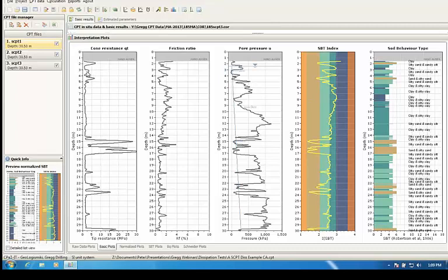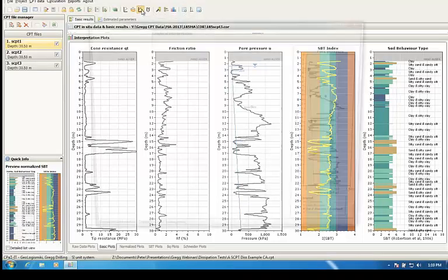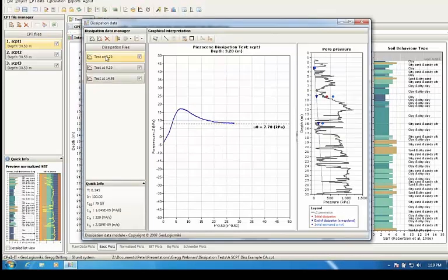Pore pressures went negative, but there are probably some positive pore pressures, certainly above where the dissipation test was done. You got positive pore pressures, so you get that more complex dissipation curve starting from negative. So yeah, it's certainly positive. This is good data, and that's a good example.